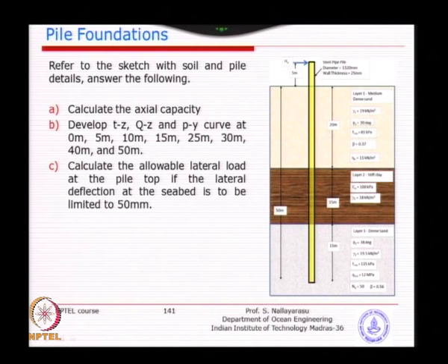What density will you use, because only one term is there. So, we need to do a normalization or take into account the weight of the soil above and find out what will be the effect. So, we need to learn this. Multi layered soil will be a problem. In fact, the API is not describing clearly what needs to be done. So, from some work done by Rees earlier, we will use the normalization procedure.